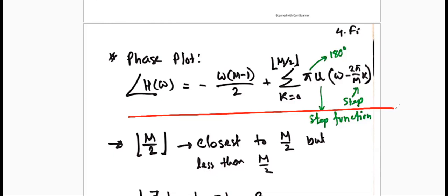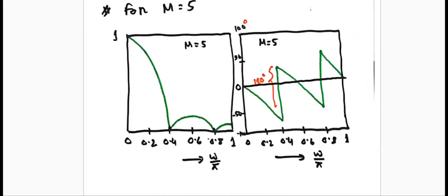I still believe that you need to concentrate on this equation more closely, but I have already discussed these things. Probably you can see this equation more closely and watch this video lecture once or twice to understand the process. However, in practice, this is very simple. Whenever you get a zero crossing or touching, at that moment, you need to add 180 degrees, and that's it. Why that is so, I have already discussed.